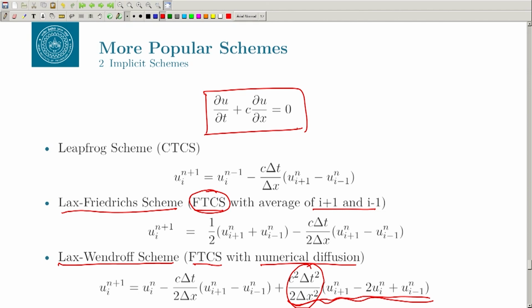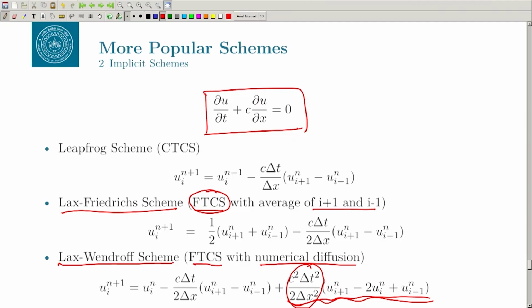We have been talking about the diffusion term, right. What do you mean by diffusion term? How does it add stability when we use the backward differencing or forward differencing, basically the upwinding scheme, but when we use the central differencing, that disappears and we then get an unstable solution. Why does that happen, right? So, let us look at the MPDE scheme, basically modified PDE equations.